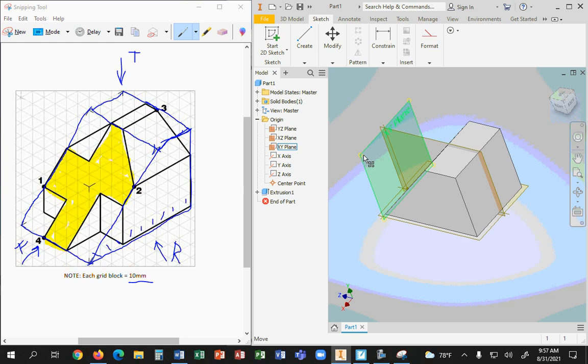Here's the reason. Anytime you create cuts off the plane, if I move my part, do you think my cuts are going to move with my part? No. Okay? That's why everything after the first move that I make, which is making my part, everything after this, I really do want to use the model. I want to attach to a face of the model. I no longer want to select a plane. Do you hear that? I want to pick the model to create future sketches. That's just a good practice to have.